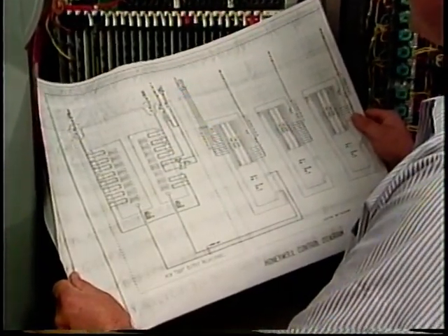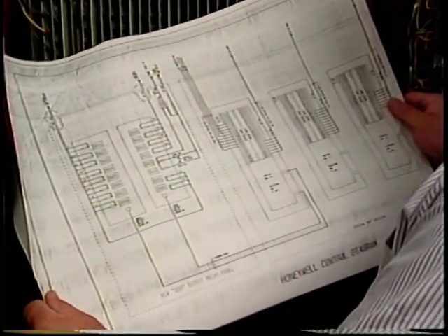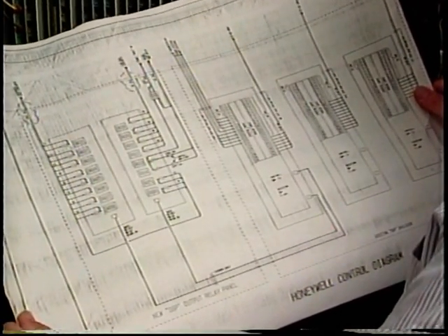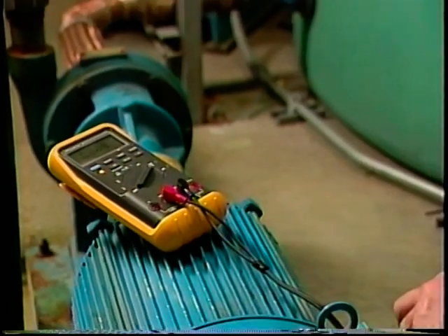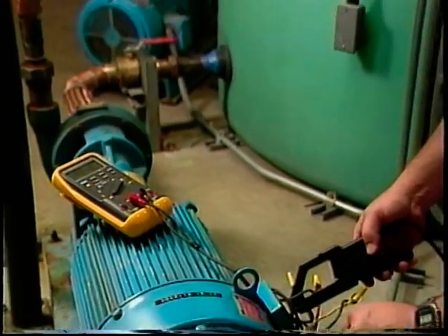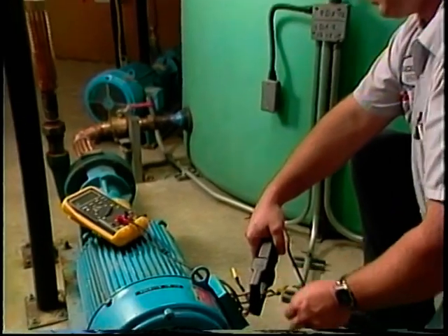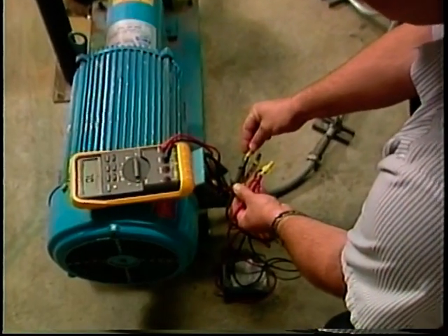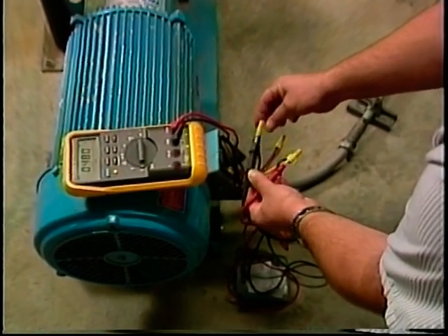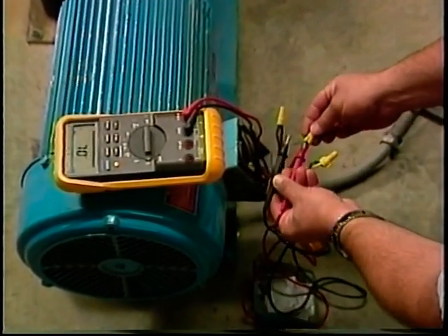Ohm's law is also used when troubleshooting to determine how a circuit should be operating and how it is operating under power. For example, when the insulation of equipment or conductors breaks down, resistance in the circuit will decrease and current will increase. By measuring a current level higher than normal, the troubleshooter knows that the circuit resistance has decreased or the circuit voltage has increased. This information can be used to determine potential problems such as insulation breakdown or a high voltage condition.